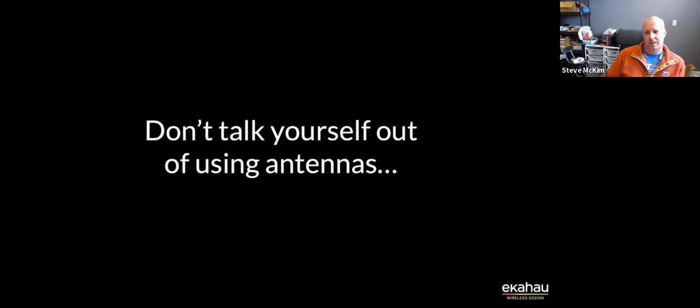I'm at the point now where I almost go to an external first, because we're not designing just for coverage anymore. I think 99% of wireless engineers are finding that capacity is the first thing they need to think about. And you get capacity by reducing your cell size, and you can do that with external antennas.